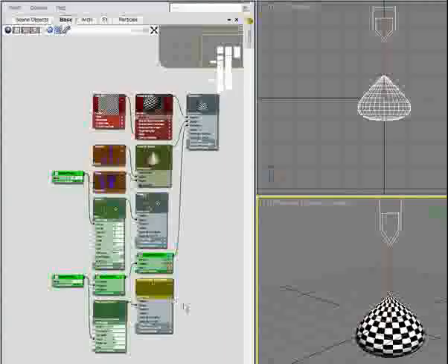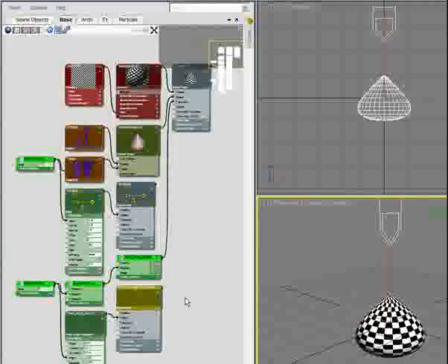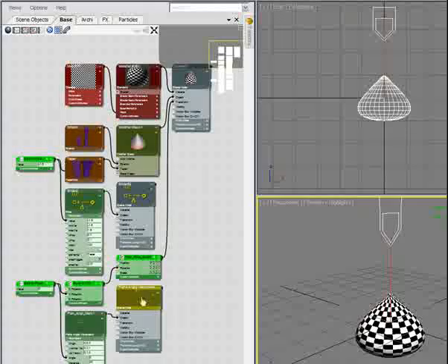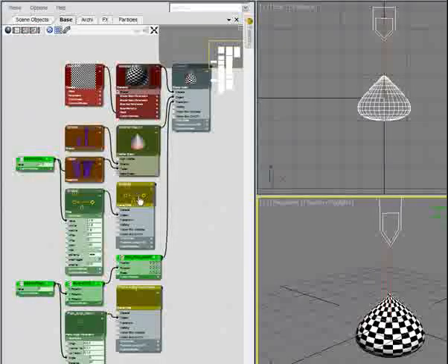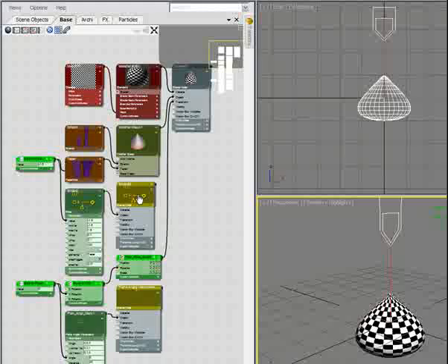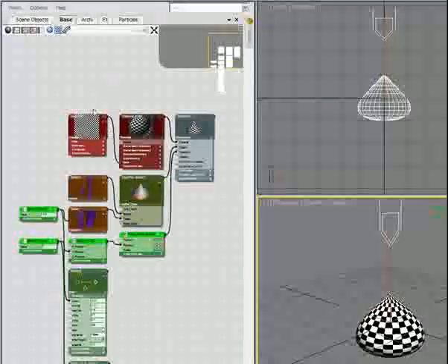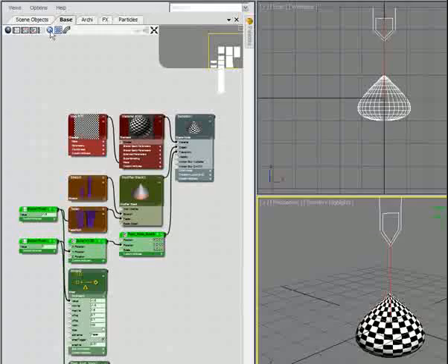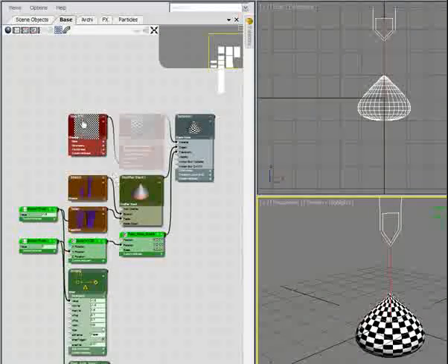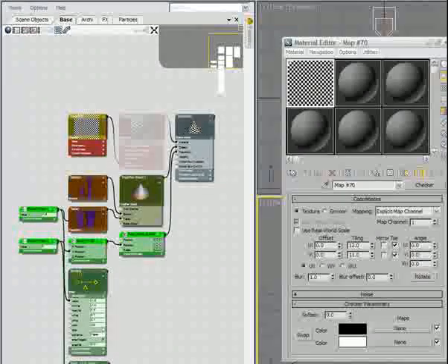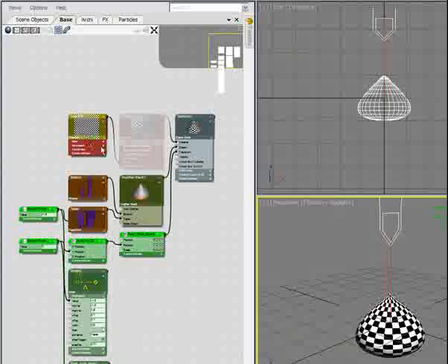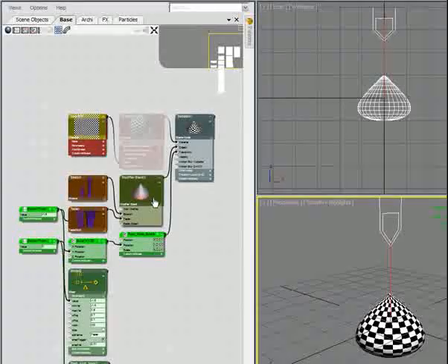Now to tidy up this view, I'm going to hide some of the things that I don't necessarily need. At this point, I might get rid of the scene nodes for the sliders here, and I'll just click delete to remove those, and then I have those two sliders. Then I might use the filters to hide some of these nodes. I might not need access to the material itself, but I might still want the actual texture to double click on that and adjust some things if I need to, or adjust things in the rollouts for parameters or coordinates.